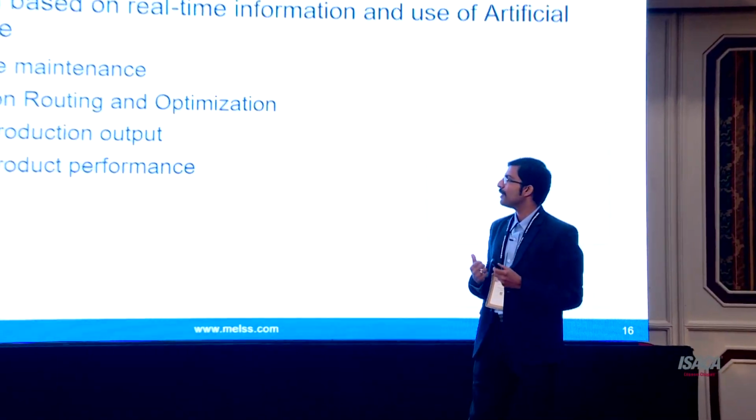Now simulation can help with production routing and optimization. It can tell you there is a possibility that this equipment is going to fail because it has already run X number of cycles, or we are monitoring the vibration on it, and based on historical patterns it looks like it is going to fail, so you don't put something through that line. It's going to cause a continuous line stoppage, so you use your other machine, right? So predictive maintenance comes in there. It talks about how you could optimize your production if you swap some parts, and the information that you gather will really help you make a better simulation. So we are talking about simulating and predicting, or forecasting, how processes are going to be using the data that is acquired.